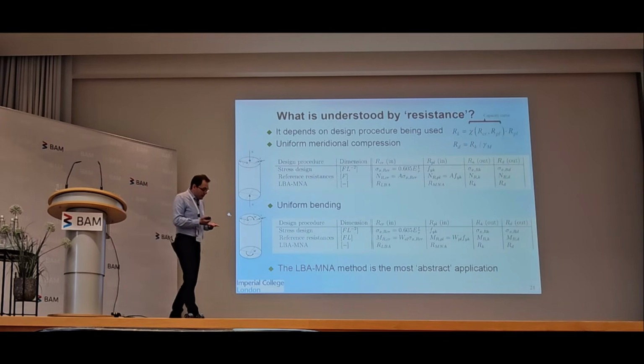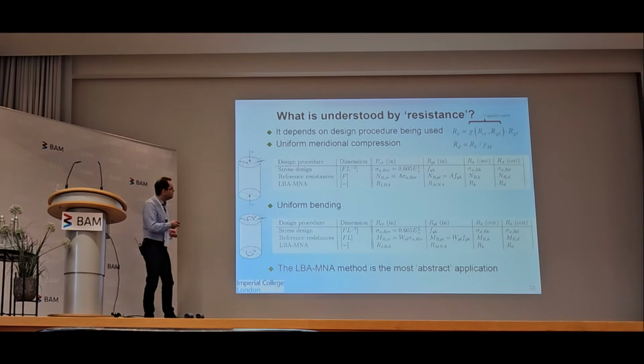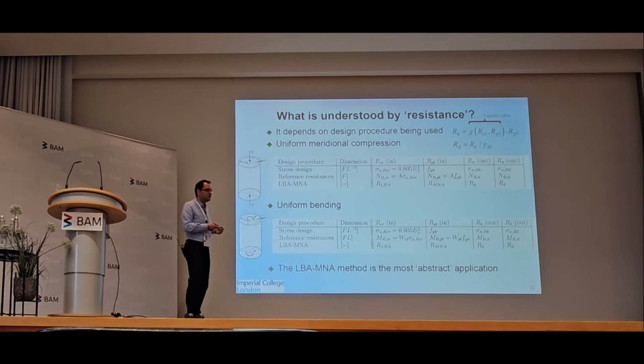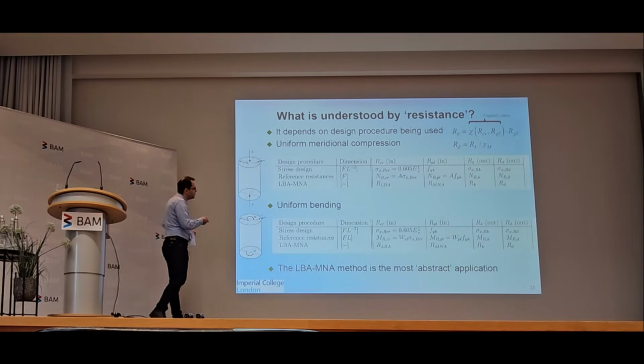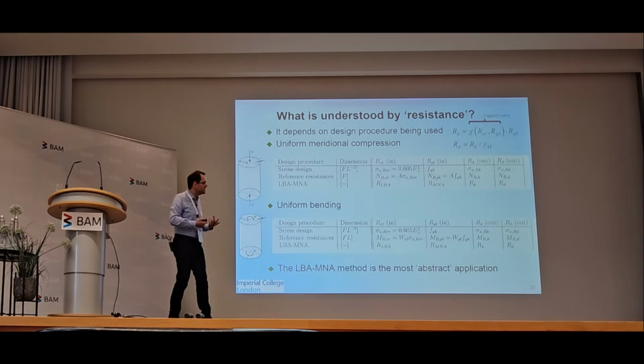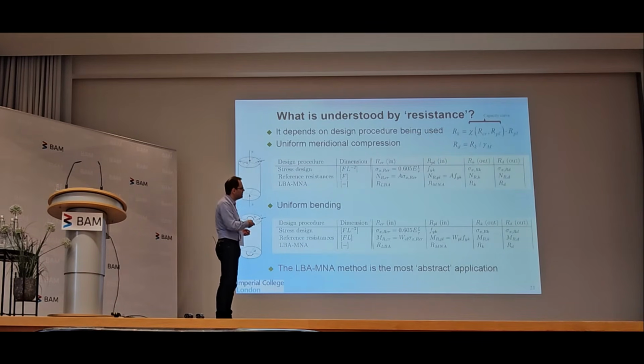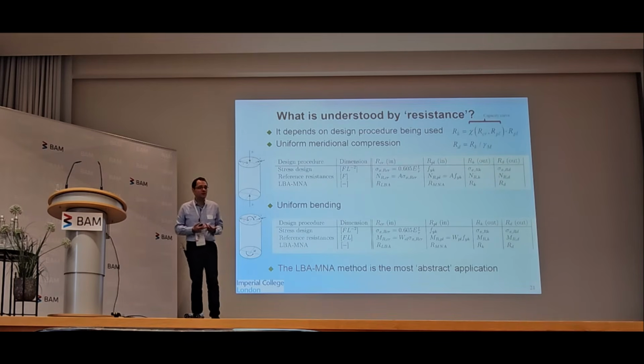So to do a buckling check in Eurocode 3 part 1-6, there are 4 methods, of which one is design by GMNIA, which bypasses this. But one of the checks that you can do is a stress design check. So you're doing a check at a point. You're usually obtaining the membrane stress state at a point. And then the input into the capacity curve is a stress with dimensions force per area. And your R critical is the classical elastic critical buckling stress. And your R_pl is your yield stress. And the R_k, the characteristic resistance that you get out, is then a characteristic stress.